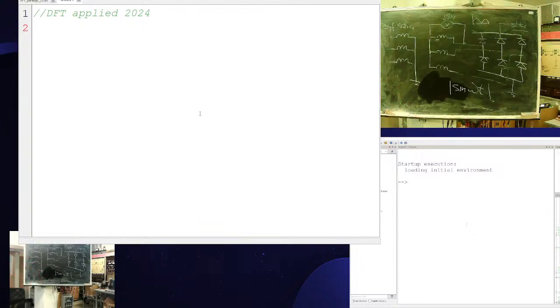You know what we got? A three-phase network here. A phase, B phase, C phase, ground wire, neutral, and PE means protective earth. They are connected. If, for example, here it's written 3 multiplied by 220 volts, and I measure like this, I will see 220. If I measure against ground, what will we get?